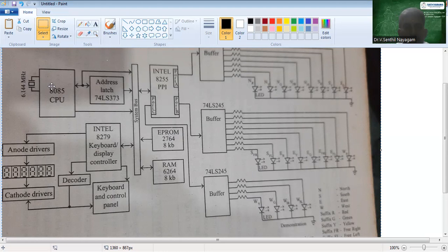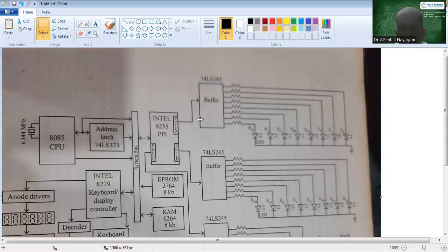Now let us consider the signal is coming out from the microprocessor, and through 8255 all the devices will be controlled. As we already know, the signal coming out of the microprocessor via 8255 does not have sufficient magnitude to drive a motor or to drive an LED. To drive means to turn on, to energize. So for that we need a current amplifier, to give the required level of current to turn on the LED.